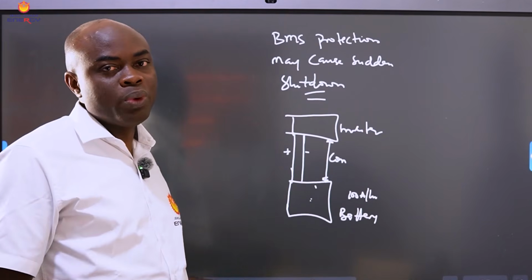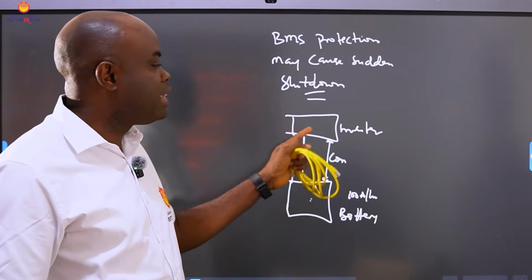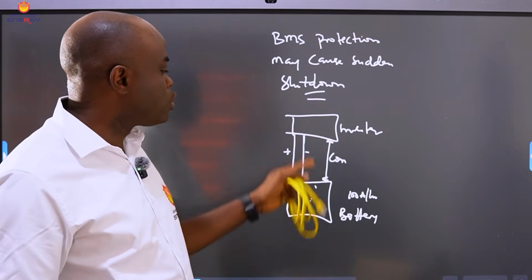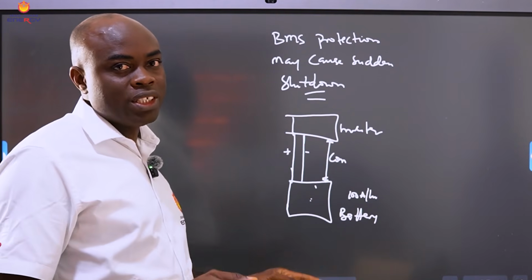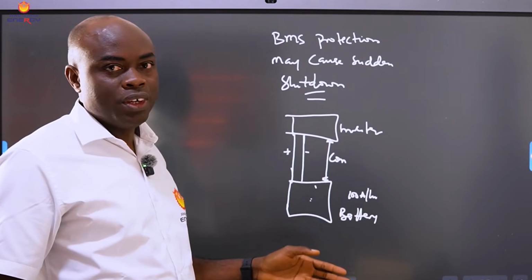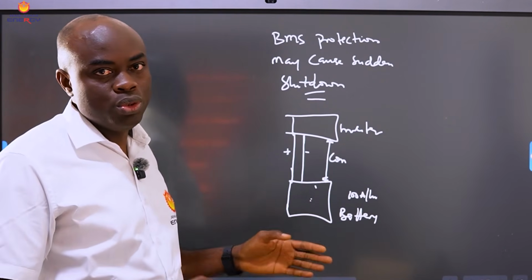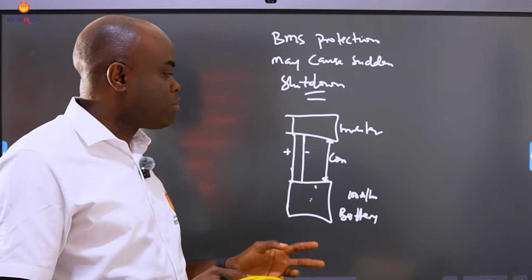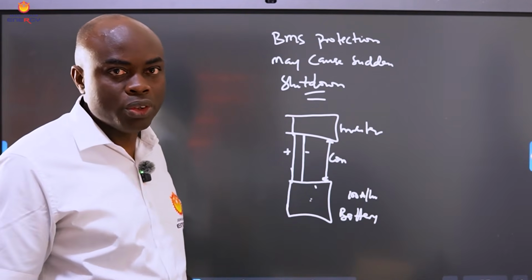As we also mentioned, when it comes to charging also, it helps to protect it. The information will be sent. Overcharging is being sent to you, cut off. Over discharge is being sent to you, cut off. The temperature is more than what is recommended, cut off.